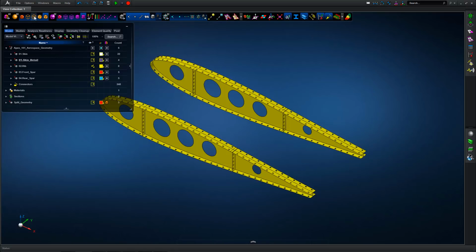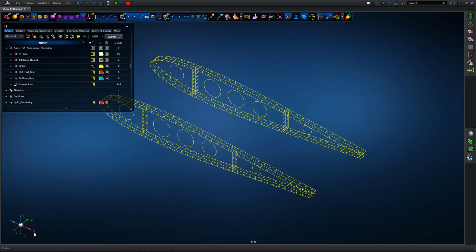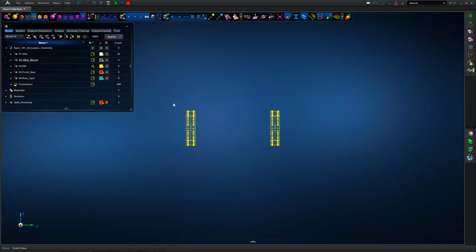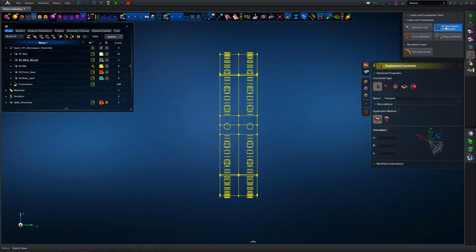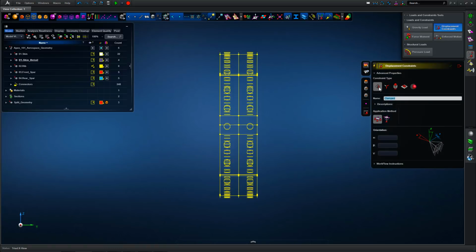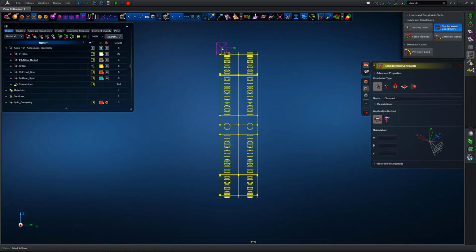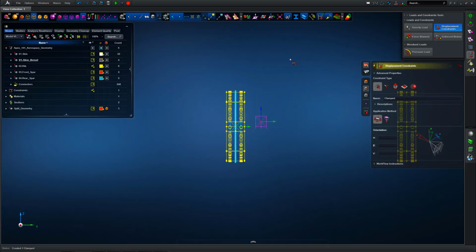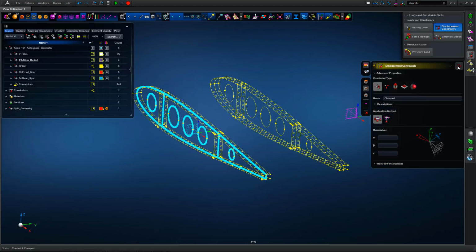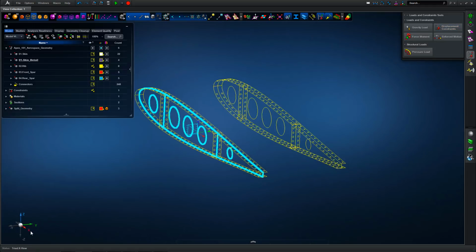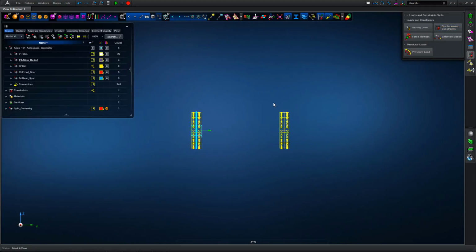So the next thing we're going to look at is to run an analysis with the embedded solver within Apex. So pretty simple in this case, but we're just going to put a simplistic wing bending load onto the structure. So on the inboard rib, we're simply fixing or clamping in all 6 degrees of freedom the edges which make up the boundary between the rib web and rib flanges, and the whole perimeters as well.